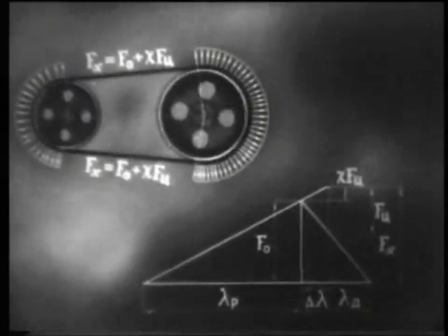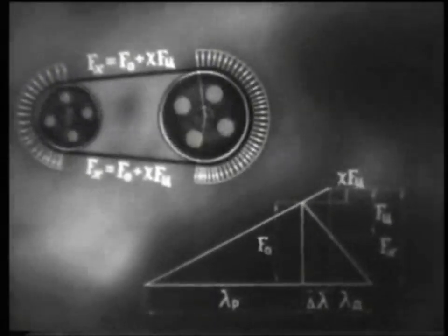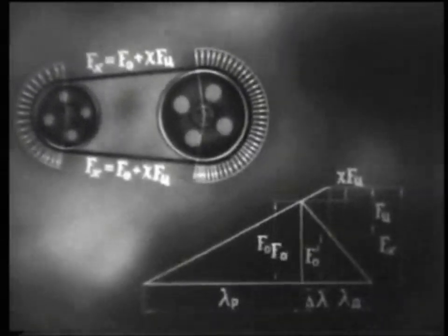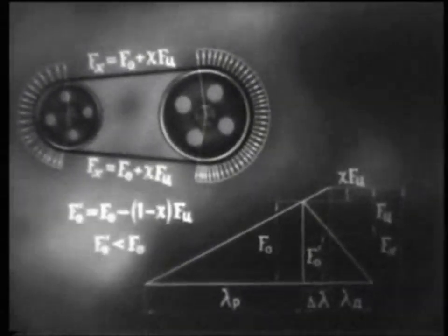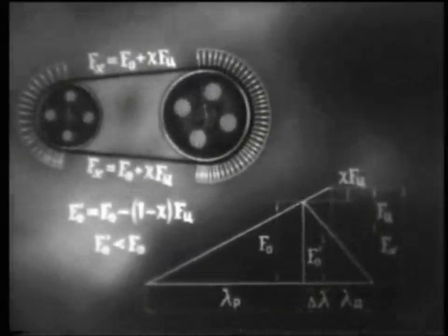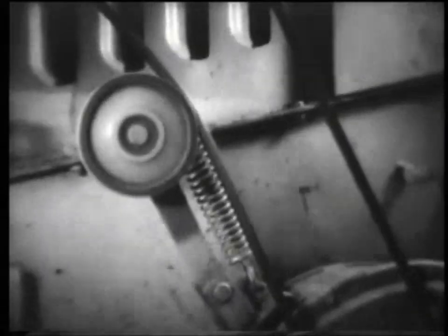Thus, with fixed shafts, with increasing speed, the force of pressing the belt against the pulleys and, accordingly, the friction forces fall. In gears with automatic tension, the clamping is determined by the weight of the load or the force of the spring and does not depend on centrifugal forces.